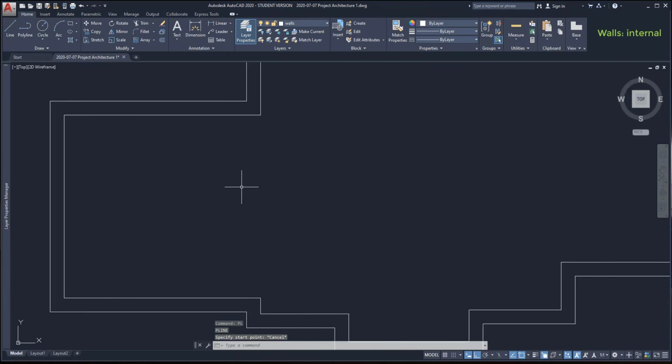For drawing the internal walls, I will be using a lot the command polyline and offset. But of course, there are hundreds of ways to make this process. I decided to start from the garage. With the command polyline, I go to this endpoint, move to the right, type 2700 and draw this vertical line towards the opposite external wall. Then I click when the object snap point perpendicular shows up.